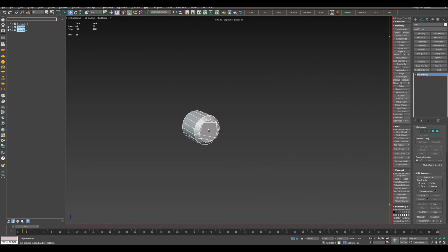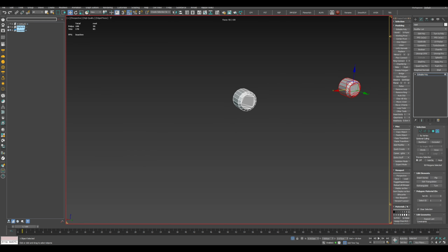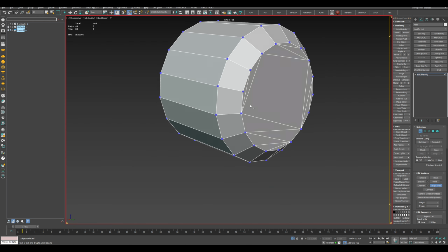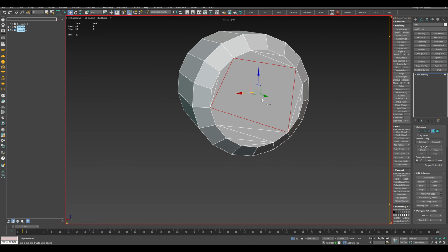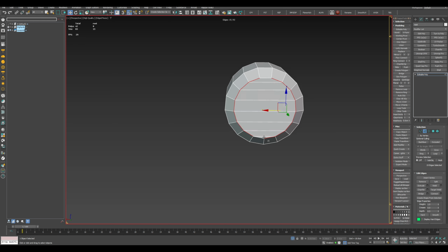And we can delete that face and those faces as well and just extrude it after. Let's add the symmetry to reset the normals and move it there, collapse and delete. And you can move this there. Let's delete that face and bridge.